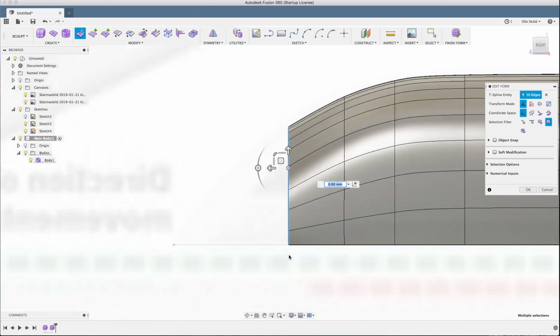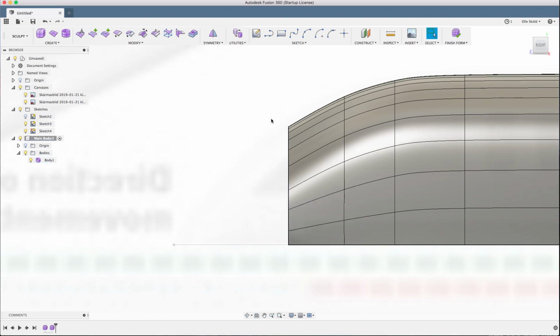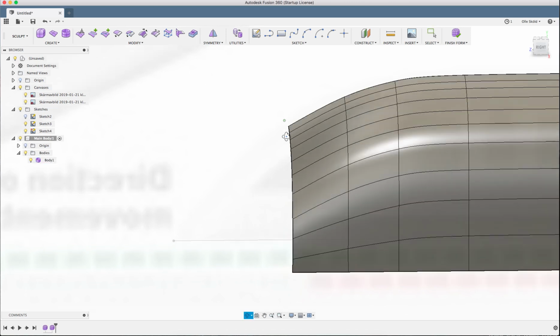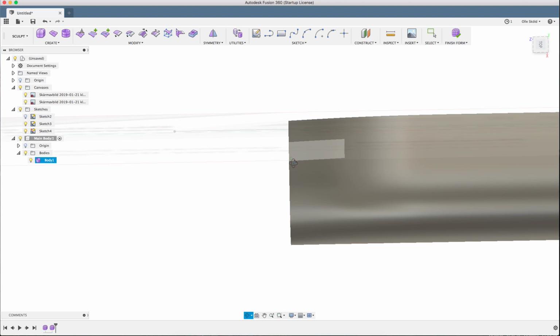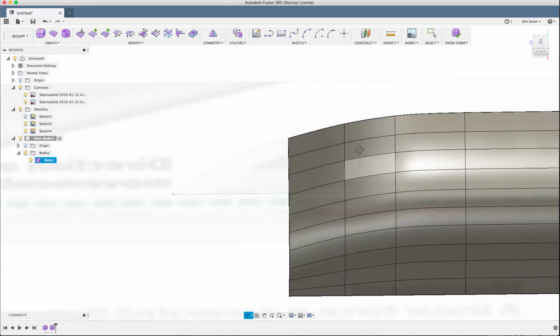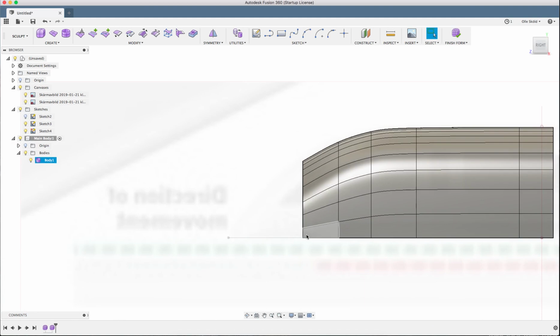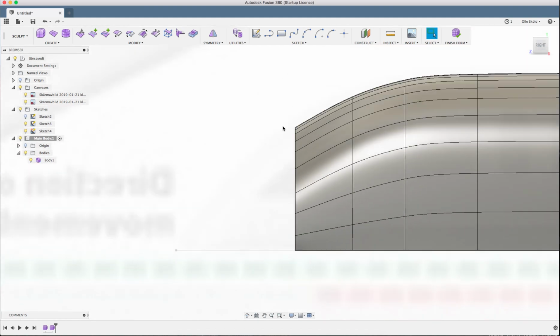And if you want it to look really tight here, you can use this tool. And if you drag it so that you see the digits here get smaller, that means that it gets more in line. So what I do, if I want a line here to be perfectly straight, I just click 0 there and enter. And that makes the line completely symmetrical in that plane. And you can also do it in this direction if you want to. Now we have not done any messing around in that direction, so that's gonna be perfectly aligned. So let's continue.